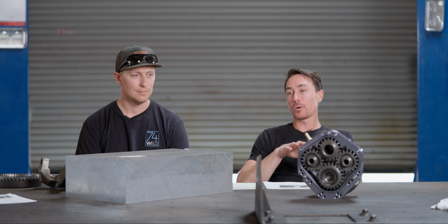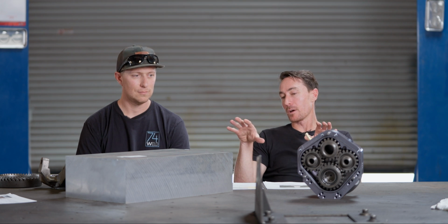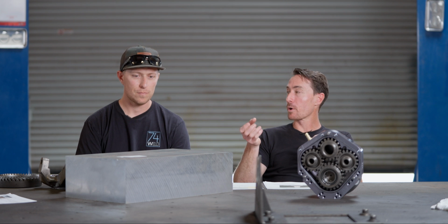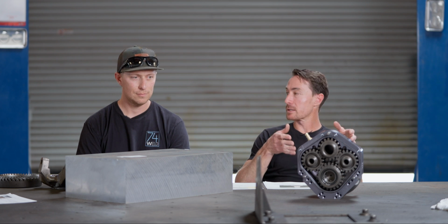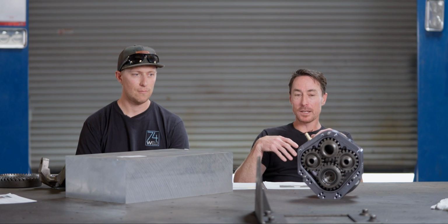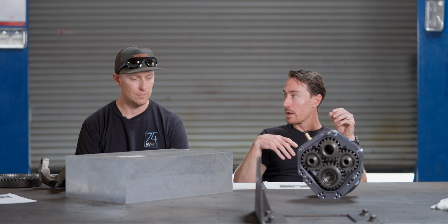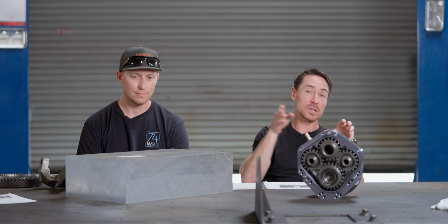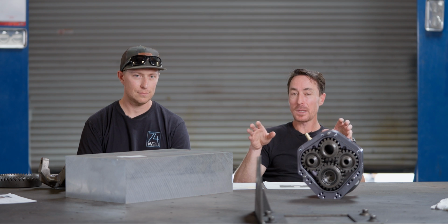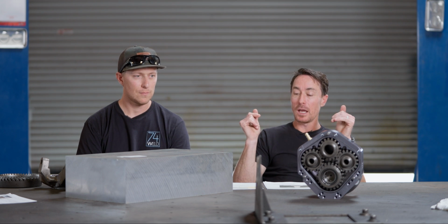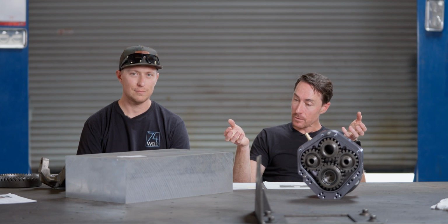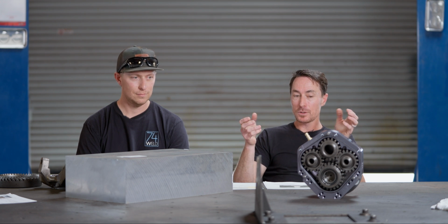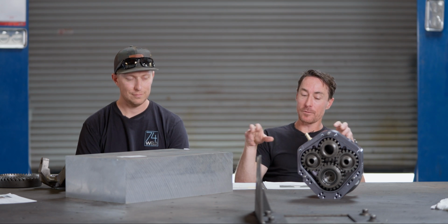I know that we're going to be forging the uprights out of a 7 series alloy. I know we're going to forge the boxes out of a 6 series alloy. The reason I'm not saying 6061 is because there's lots of different options, or 7075, because again, there's lots of different alloys in those 7 series, and we will carefully and slowly work with forging manufacturers or forging houses to pick the specific alloy for our application.